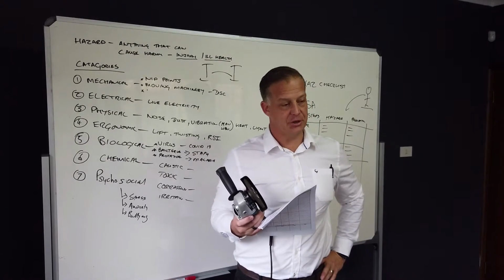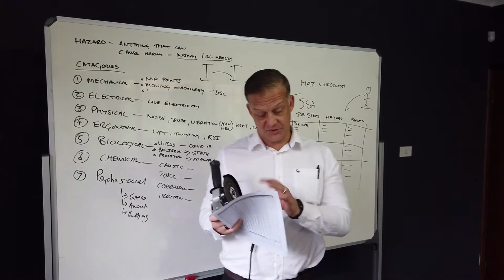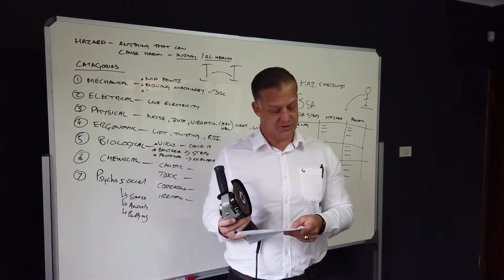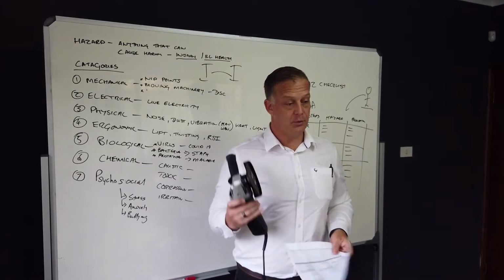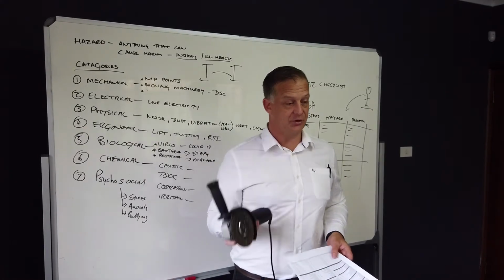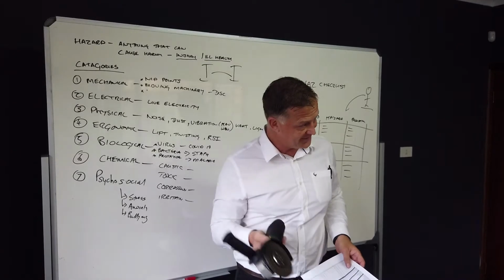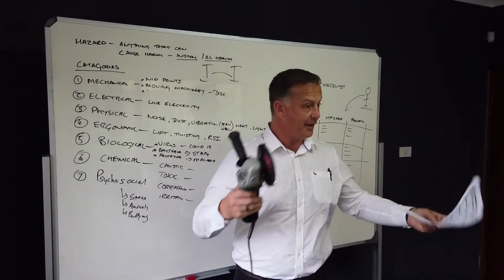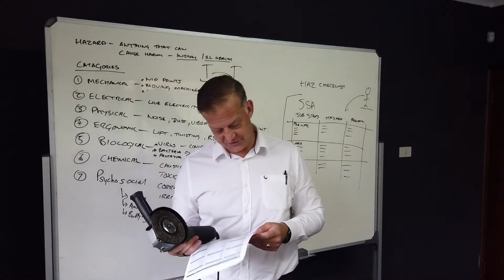Do you think there's friction? So friction is going to result in an excessive amount of heat. So there's going to be a significant amount of friction. So yes, sparks, grinding, you can tick those off. Pressurized systems. Now, one thing that we need to be aware of, particularly when we're using a grinder, is that there have been some terrible incidents when people have cut into old LPG gas tanks, etc., that still have gas inside them. Okay? So that you're not grinding into pressurized systems.